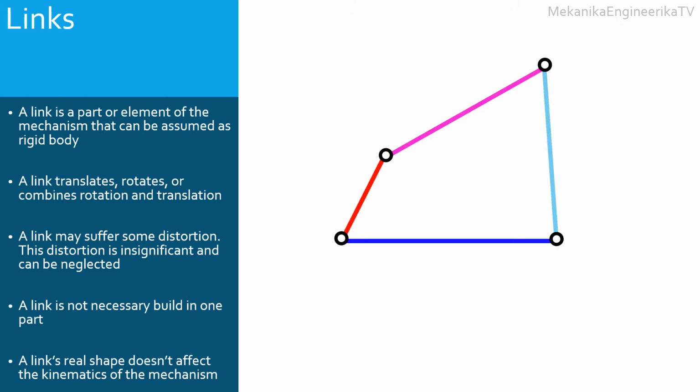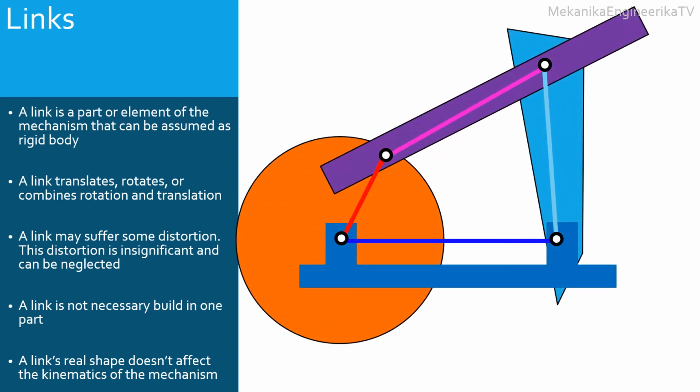A 4-bar mechanism is not necessarily built up from rod-shaped links. The bars are kinematic representations of binary links that rotate relative to each other. Behind the kinematic diagram of a mechanism, there is a real shape for each bar. However, the most important is the nature of joints and their relative position.